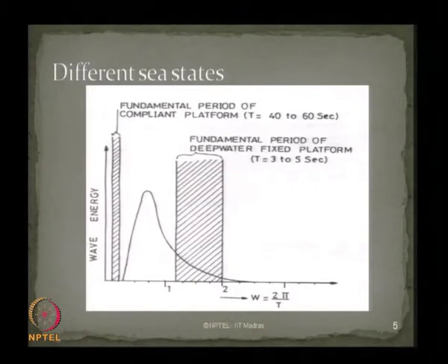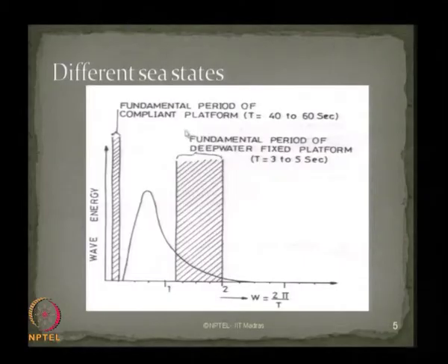Alternatively, if you look at the type of platform which is to be installed in these sea states, then the fundamental period of compliant type platforms varies from 40 to 60 seconds, which has been shown in the wave frequency here at a lower frequency, whereas the fundamental period of deep water fixed platforms, which generally varies from 3 to 5 seconds, has been shown in this range here.